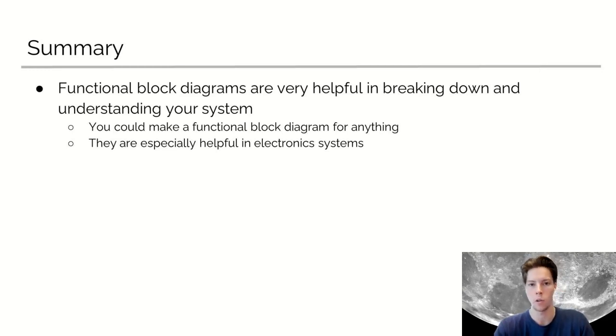And specifically for the LunaSat, it shows how power is taken in, converted, and sent to RF and all the sensors, and how we're able to read in the data from the sensors to the microcontroller and back out through the RF. And then also how we're able to test functionality through our laptop and the SPI interface. So it really shows how everything works together and how the system is able to operate successfully.